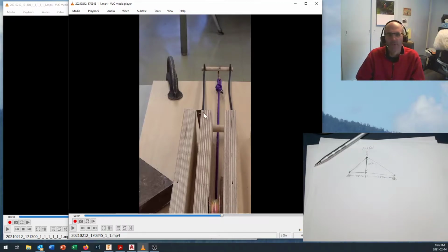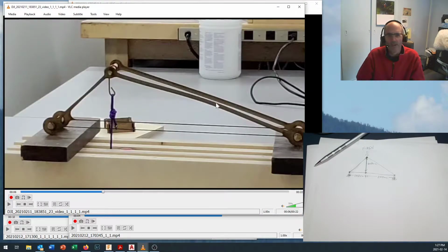and both quite a bit higher than we would have predicted if I just had a single piece pinned at each end right in here. My predicted strength for a single piece pinned at the end was going to come in, I think, around 17 newtons or something like that. And now if you take the 80 or so newtons that we had coming down in here, 80, 90 newtons, it was somewhere in that range. Split that across the two members. Each one of these is supporting 45, almost twice as strong as what we predicted, and actually quite a bit stronger than in the tests that we saw right here, where this was also holding a lot more than 17.